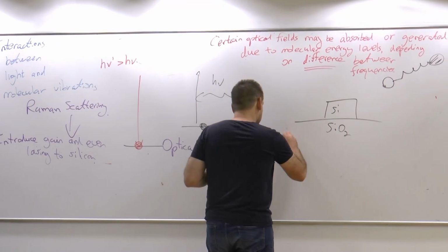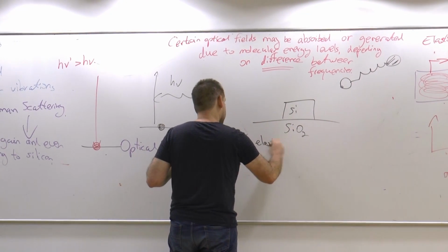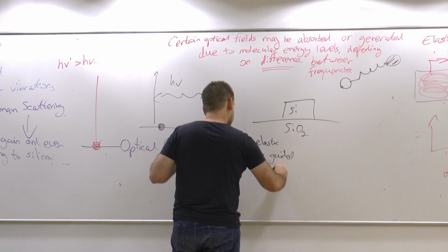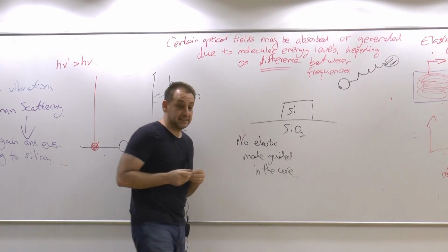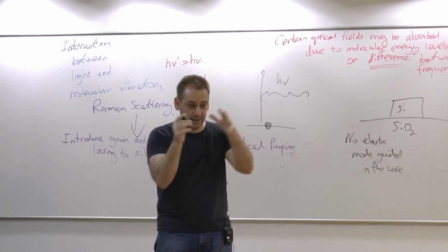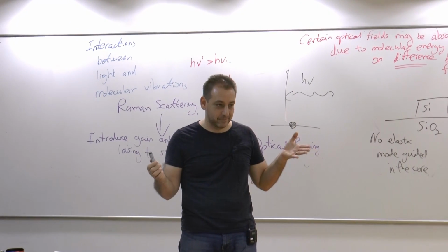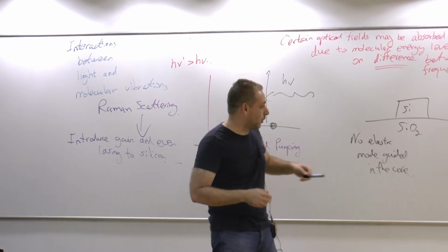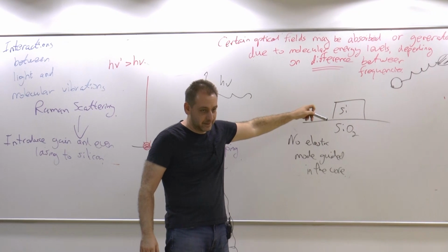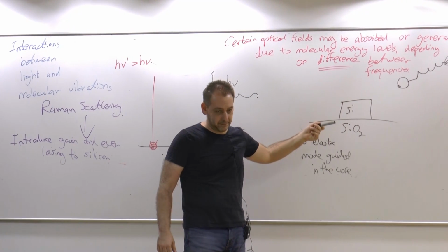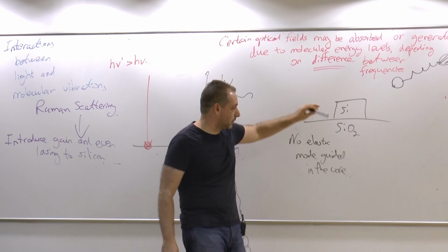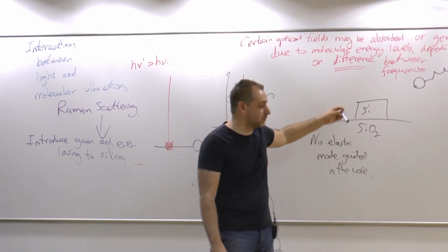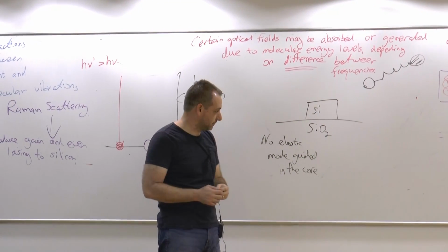So there is no elastic mode guided in the core. It is as if you try to build your optical waveguide with low index in the core and high index outside. Light will never stay in a core like this. There is no guiding. So when you examine the SOI layer stack, we find the mechanical equivalent. We can support light in the core very easily. We cannot support sound in the core because it is not guided. It is running away down the silica.